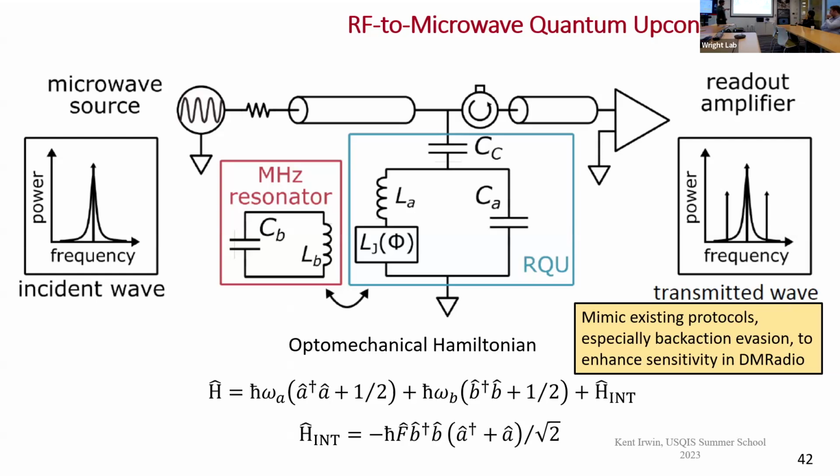And the idea is you couple your low frequency resonator to a gigahertz lithographic resonator by a variable inductor. So flux from the resonator goes into the lithographic resonator and changes the frequency, and then by interrogating that frequency change, you can do very sensitive flux sensing.